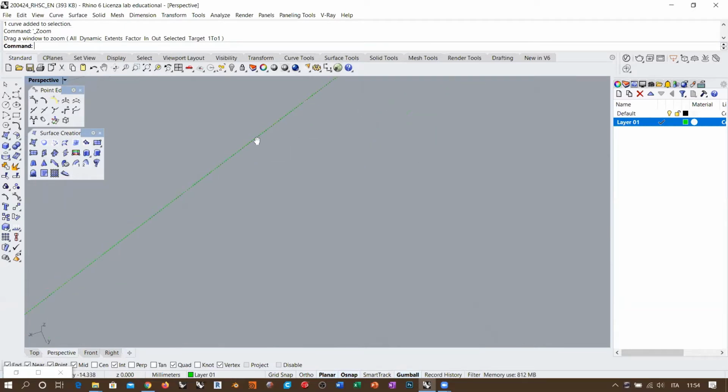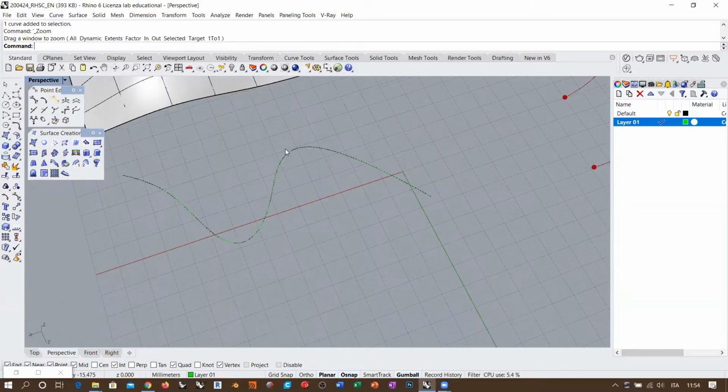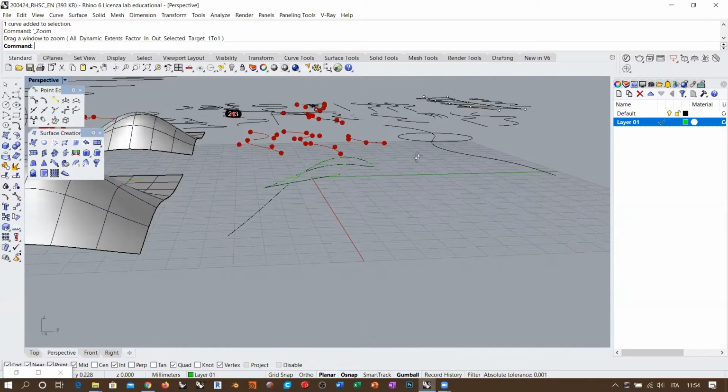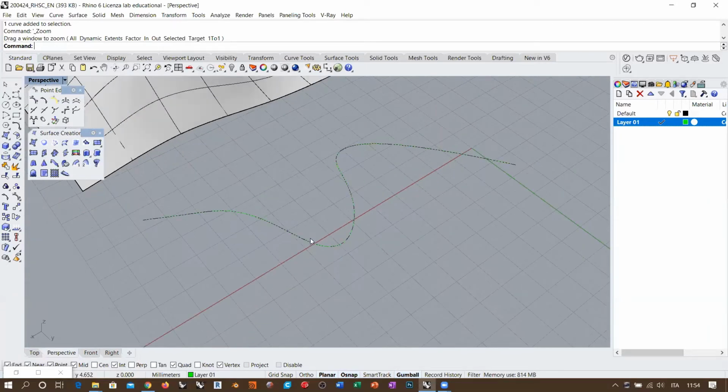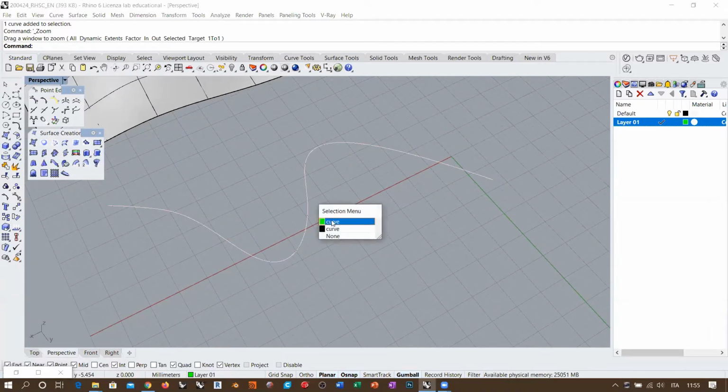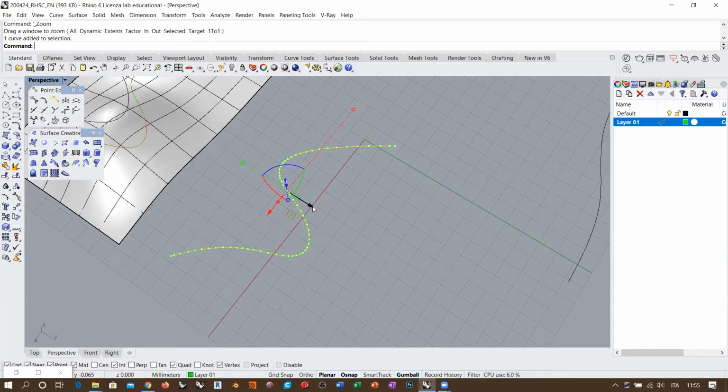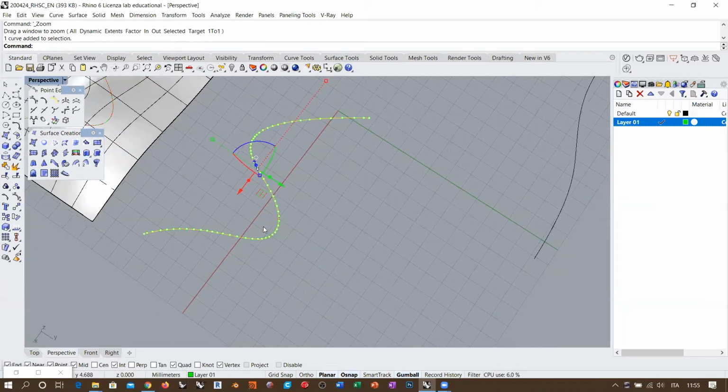Let's see if we manage to see some, yeah, you see that there is this very, very small difference. This is 1 micron, basically, maximum deviation, okay? So this is probably the best way of rebuilding a curve according to the document tolerance. Fitting doesn't take into account the even distribution of control points along the path, okay? Because it is based on fitting tolerance.